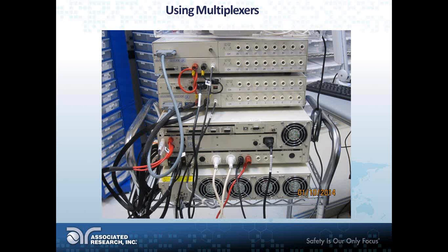High voltage and high current is being routed from the safety analyzer into the scanning matrices, and then controlling these scanner channels can route that high current or high voltage to different channels, and those channels can be connected to different applied parts or points on your device that's being tested, hence allowing our users to run multi-point testing on their products.